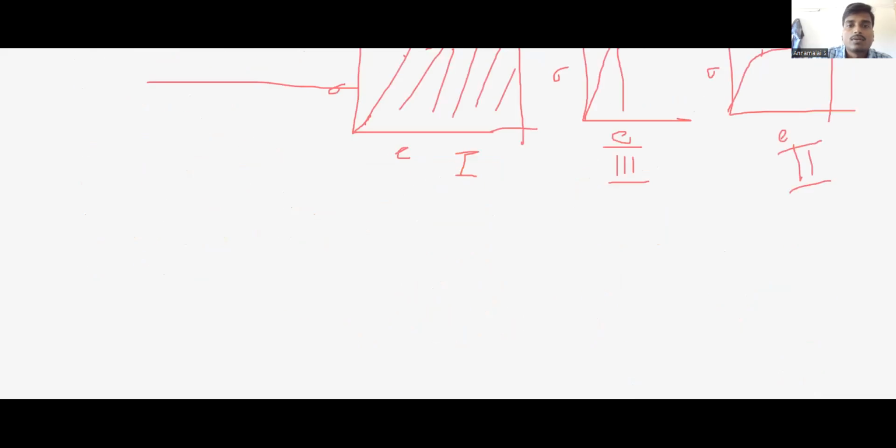Now we are going to discuss the high speed steel, shortly called HSS. If you go to your machining lab or workshop, you can find HSS in all the lathe machines. In our laboratory, we use mild steel as the workpiece for all operations, whether it is turning or milling. In order to machine mild steel, we use high speed steel as the tool material.